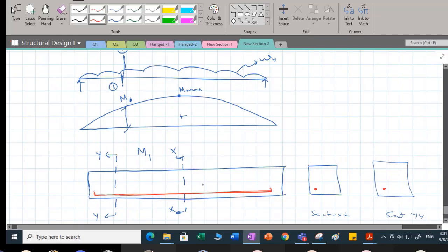So I have placed it over here. Again I am placing 1 more bar. You see, 3 bars have been placed. Now 3 more bars have to be placed. This time I am curtailing the bar. Please see, this is the bar which I am providing, and I have curtailed it. I am not providing this bar throughout the length of the beam. I need to specify at what length I should curtail the bar. So curtailment means cutting the length of the bar.